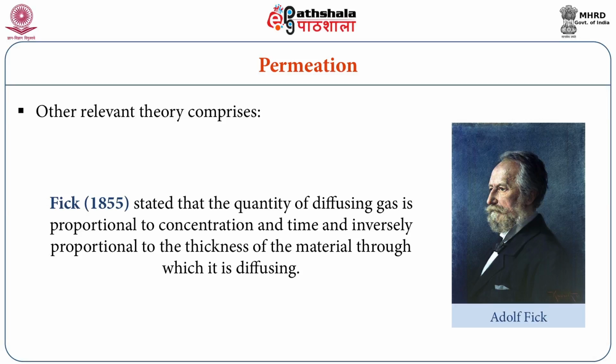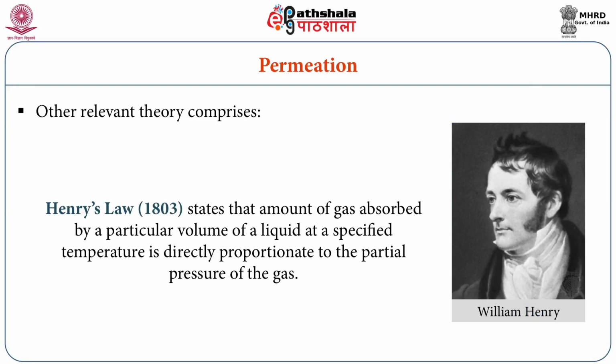It states that the quantity of diffusing gas is proportional to concentration and time and inversely proportional to the thickness of material through which it is diffusing. And the last one is Henry's law, stated in 1803. It states that the amount of gas absorbed by a particular volume of a liquid at a specified temperature is directly proportionate to the partial pressure of the gas.